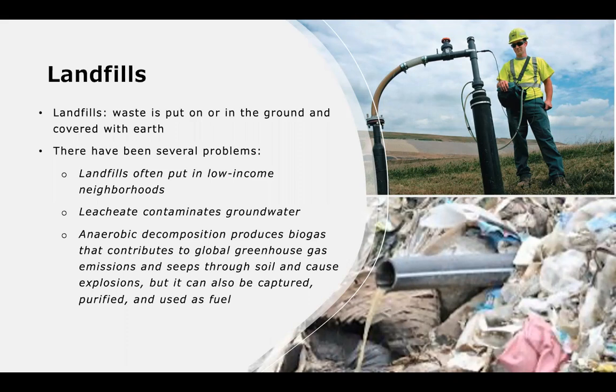Treatment and management of municipal solid waste, and also some hazardous waste, can be done using landfills. Landfills are an engineered system where waste is put on or in the ground and then covered with earth. These landfills have an impermeable membrane that prevents the leachate from the waste from contaminating groundwater, although there are still instances where the leachate will leak out from the landfill and contaminate the groundwater or surface waters. The other problem, as mentioned before, related to environmental justice, is that landfills have often been historically placed in or near low-income neighborhoods.